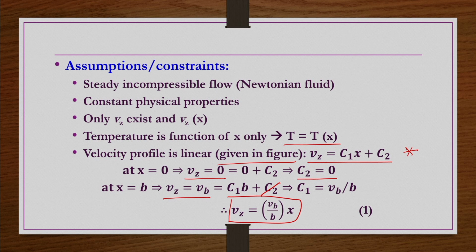So even if the boundary condition of the moving surface has been changed for temperature, the velocity profile is not being affected. What does it mean for these problems? The velocity profile is affecting the temperature profile, but the change in temperature, the non-isothermality in the system, is not affecting the velocity profile. Neither is the rheology of the fluid affecting the velocity profile, because of the narrow gap and all that. So because of the flow, the temperature profile is changing, that we are measuring now.